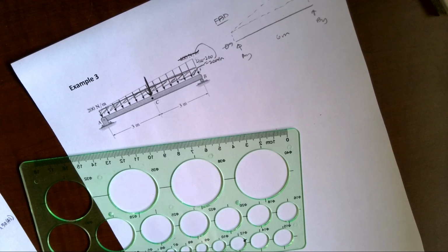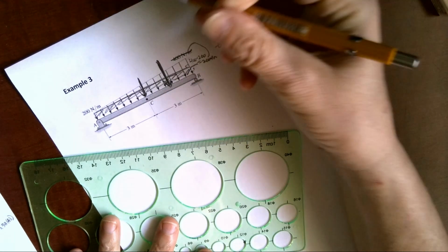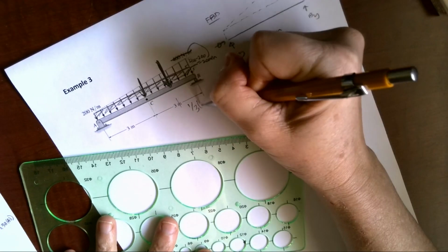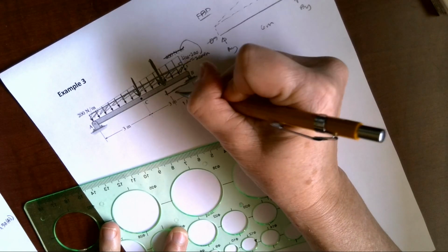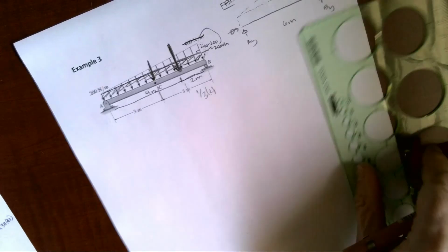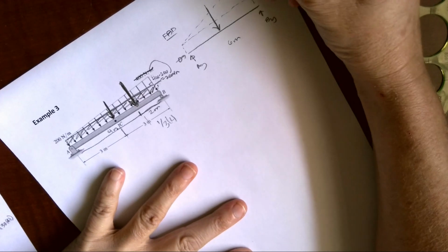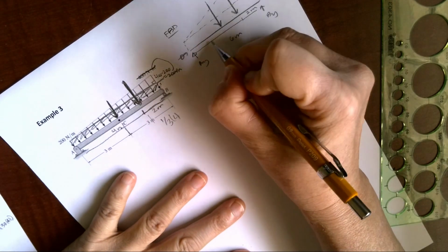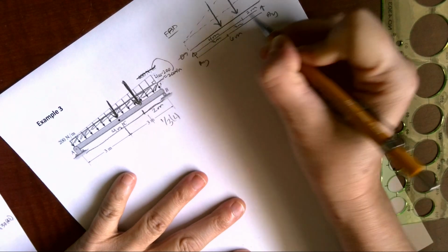Okay. And with a triangle, we know that we are 2/3 from the end with the right angle. So if I have 6 meters total and I march back 1/3 times length, then I will get that this is right here 2 meters. This length is 4 meters. And my rectangular section has the centroid right in the middle. So we are going to have one right here and one right here. This is 2 meters, 4 meters, 3 meters, 3 meters. Okay, I just like to go ahead and mark everything that I can.